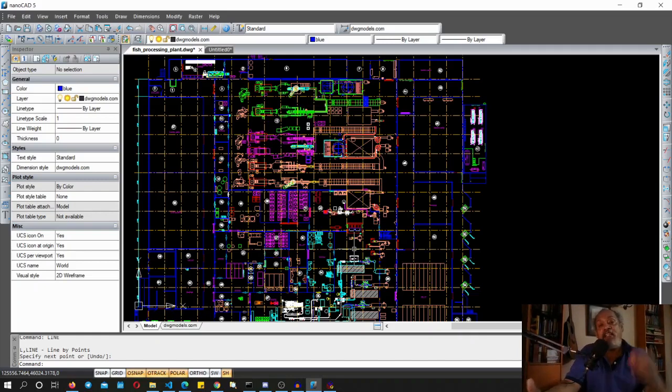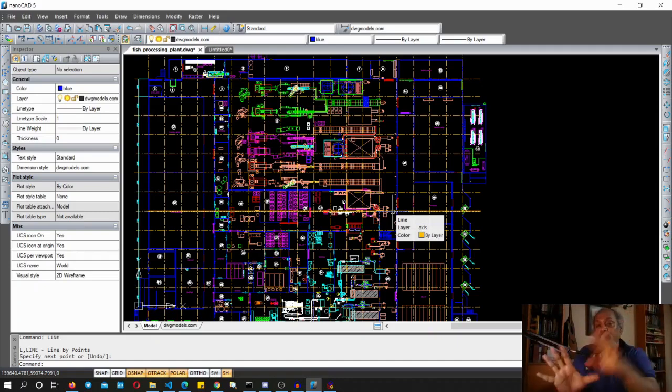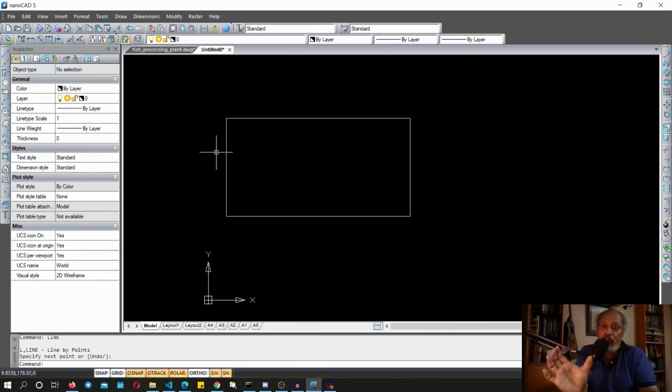But the problem is that the software allows you to keep the data in a corrupt manner where one of the edges is missing or a few of the edges are missing, and then even if you put it back, if all you have to do is forget to do the join, it remains in a corrupted state, because that one part of that object was a polyline, like these three segments would have been a polyline, and that is kept separately in the file, and the top line is kept separately.